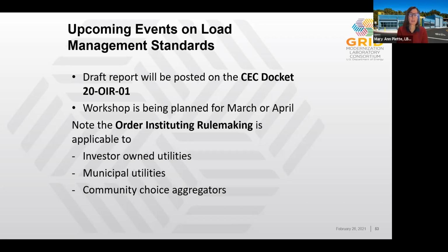So if you're getting an RTP signal, you'd get it continuously. Now, it may be that you have a day ahead price. So at 3 o'clock on Monday, you get 24 prices that give you the hourly price for the entire day. And that's kind of a rolling thing. And the concept is then you could schedule your heat pump water heater to charge before the high price time. And you could schedule your dishwasher not to come on until the price is low. Some of that may be manual, that you let people see the price, and they could get a smartphone app. So there's a lot of interest in creating the underlying infrastructure to allow this to be happening. Go ahead to the next slide.